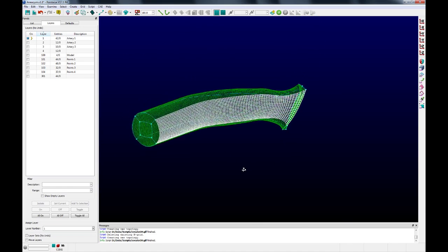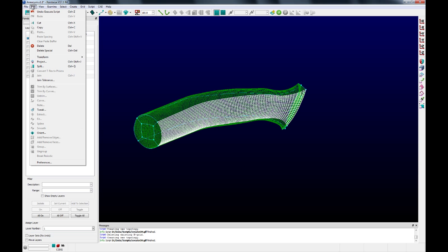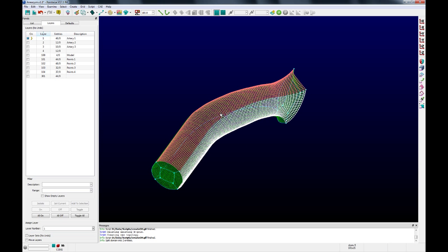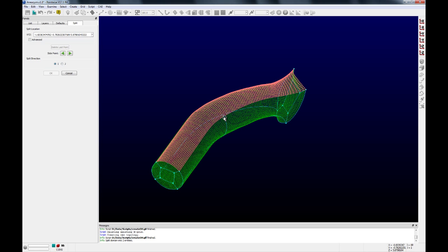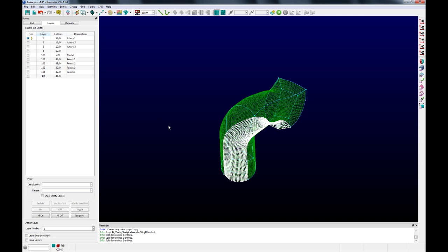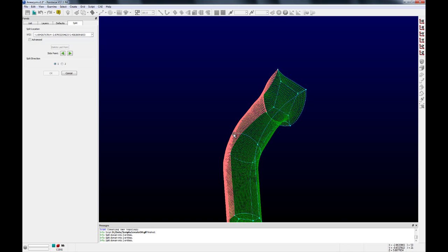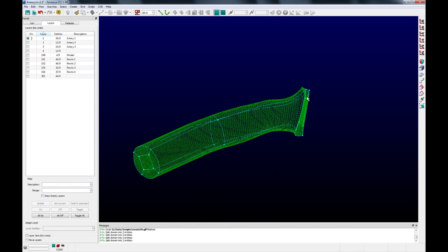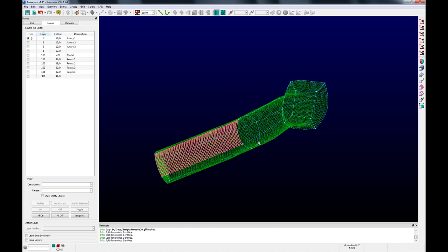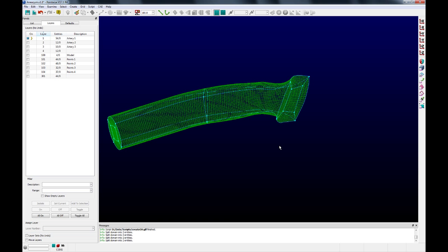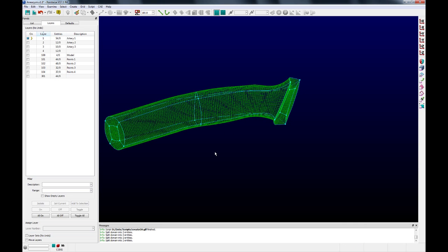and then the other where the artery starts to twist and turn as it enters the junction. So to do that, we're actually just going to split these domains with edit and split, and we're going to pick a point about halfway down. We're going to repeat this using the accelerator, Control Q, for the other three domains, and that will allow us to divide this problem up into two portions. One at the entrance, where the artery inlet is over here, and then where the artery enters the junction. Whenever we're running the blocks solver a little later, you can see why it would be useful to kind of isolate this region of high skew and everything from this nice uniform region at the beginning.